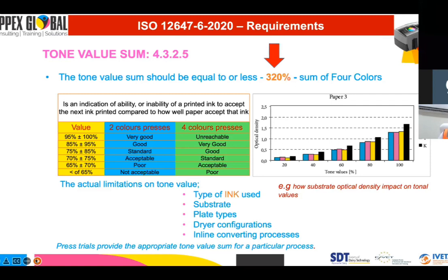But this 320 is really a higher level, and that's when we add up the ink percent in any part of the image or graphic should not be more than 320. And many of the programs will do a stain to show you this. If the pre-press department has done their job and applied the correct ICC profile, when it comes to us, it won't be like this, and it won't be greater, and we won't have ink pooling and problems with smudging and smearing and drying on our print process.